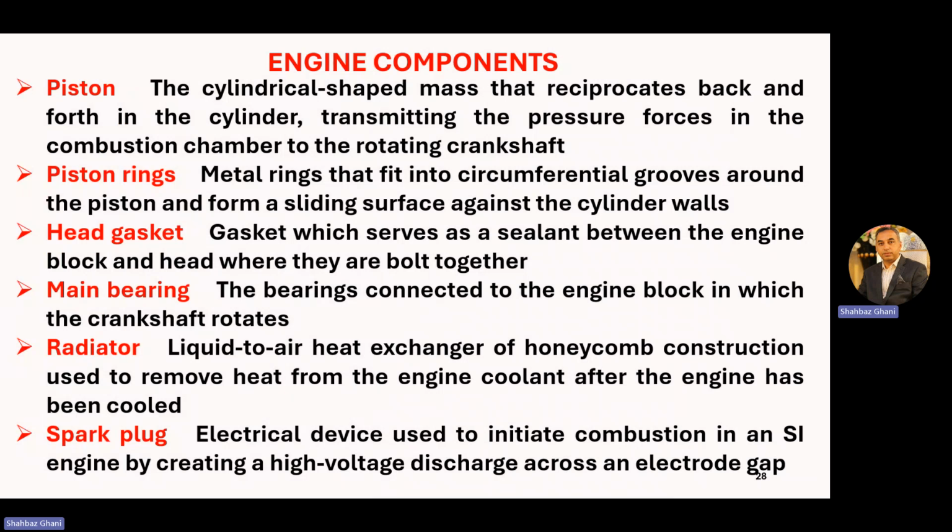Now the piston. The cylindrical shaped mass that reciprocates back and forth in the cylinder, transmitting the pressure forces in the combustion chamber to the rotating mechanism. The piston is attached with your connecting rod, and then the connecting rod is attached to your rotating crankshaft. Basically, it's a cylindrical shaped mass that reciprocates back and forth in the cylinders, transmitting the pressure forces in the combustion chamber to the rotating crankshaft.